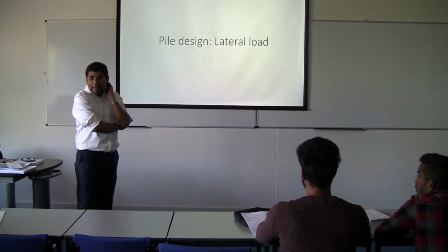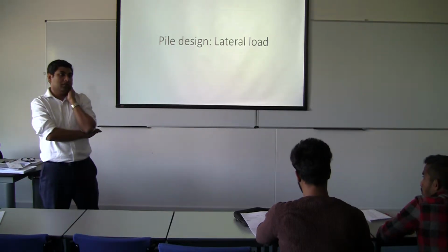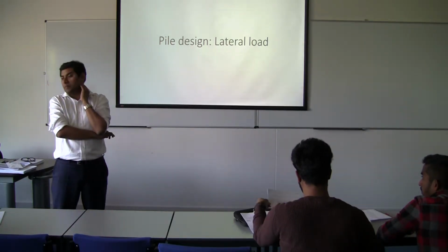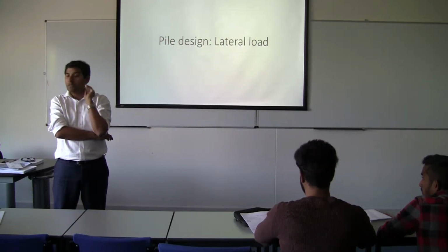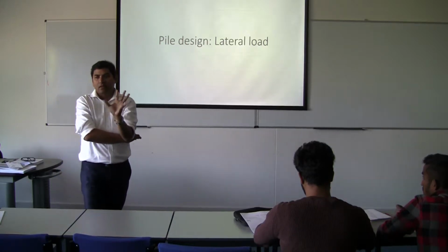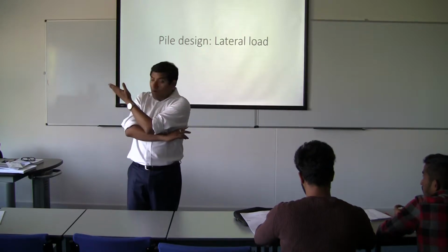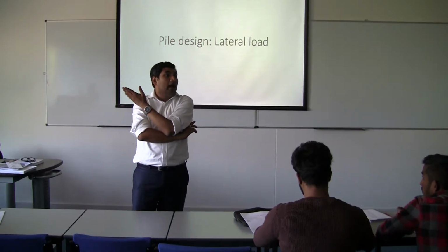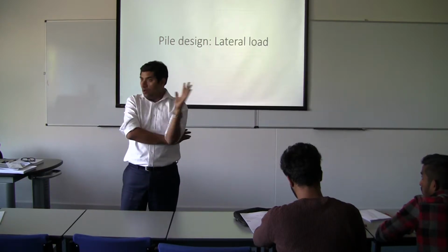However, another thing is lateral load. So often piles do carry lateral load, right? Can you give me some examples of lateral load on piles? Wind turbine. A wind turbine is a big lateral load, a moment. Anything other than that? Waves, wind. Waves, wind, yeah? In a normal building, you have wind load. If you have a very tall building, there's a wind load.